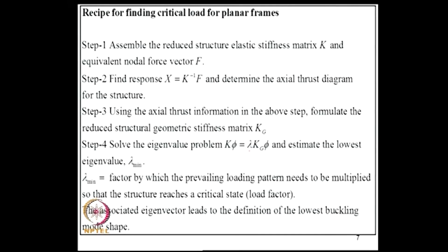So, that lambda, that is alpha, now we will estimate this lambda min, and this is a factor by which the prevailing loading pattern needs to be multiplied so that the structure reaches a critical state. So, this factor is also called the load factor. The associated eigenvector leads to the definition of the lowest buckling mode shape.